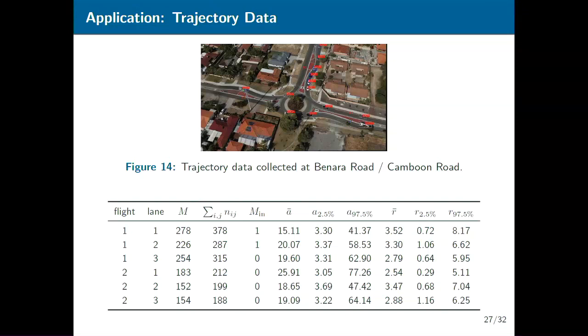If this is a roundabout, how can it have a major lane? Does your setup rely on there being a lane that has right of way? Yeah, so for every entry lane over here, it will be the minor lane, and the major stream traffic is the circulating flow.